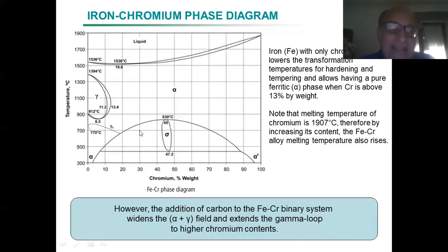In reality, the amount of chromium might be variable across our material. In practice, we might have the formation of some intermetallics in some places, which reduces the resistance of our alloy.